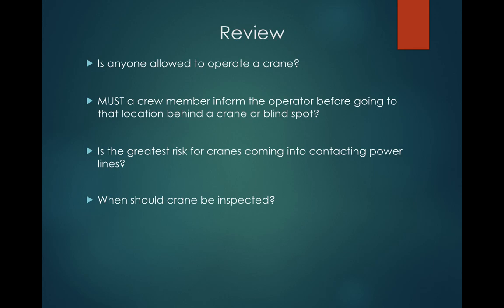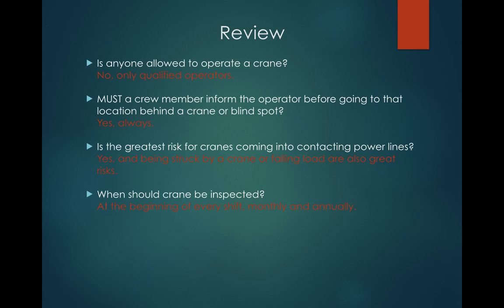So just to wrap this up, some questions here. Is anyone allowed to operate a crane? Must a crane member inform the operator before going to that location behind a crane or blind spot? Is the greatest risk for cranes coming into contact with power lines? And when should a crane be inspected? So the first one is no, only qualified operators. Second one is yes, always. Third one, yes, and being struck by a crane or falling load are also great risks. And when should the crane be inspected? Just went over it. At the beginning of every shift, monthly and annually.